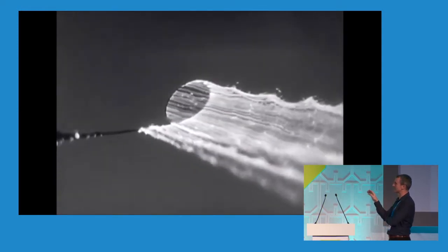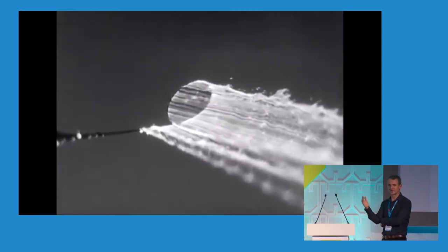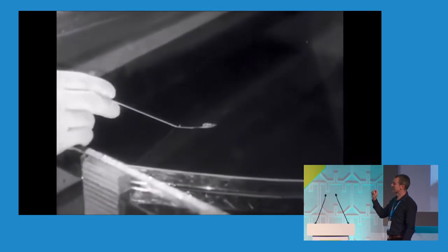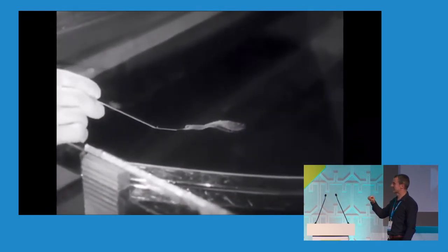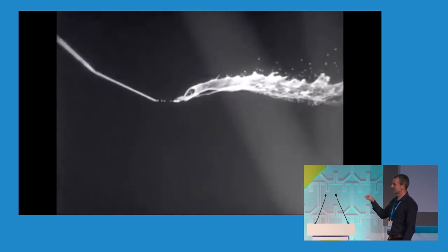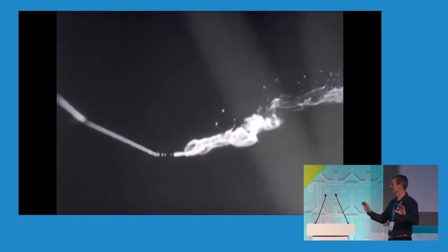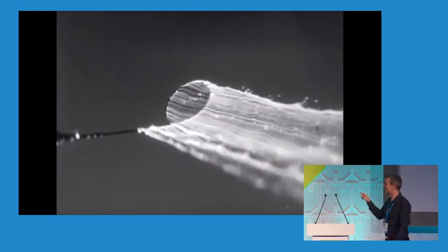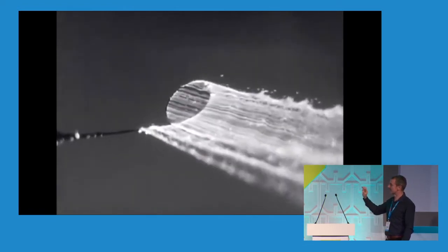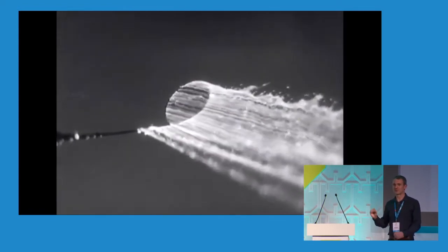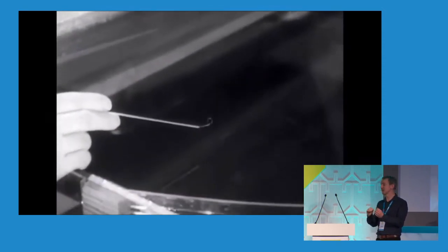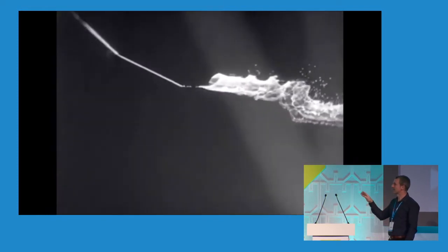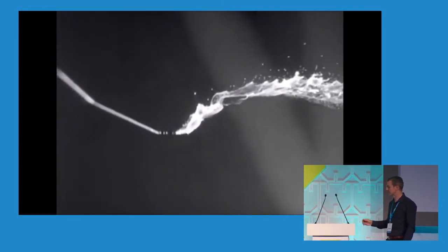But this is somebody that was kind of at the forefront of trying to visualize what was happening with flow fields. In this case, it's an electric wire connected to a DC supply. And when you submerge that in water, which I know is a bad thing to do, so I wouldn't recommend doing it, but submerging it in water, you get electrolysis happening. And that releases these tiny hydrogen bubbles, which just so happen to be the right buoyancy to remain in the flow and not get separated out. So it's a really powerful tool that they use to understand what was going on with different flow fields.